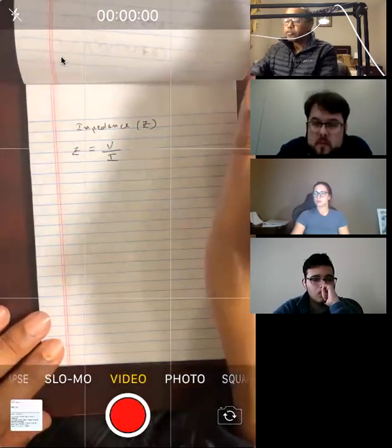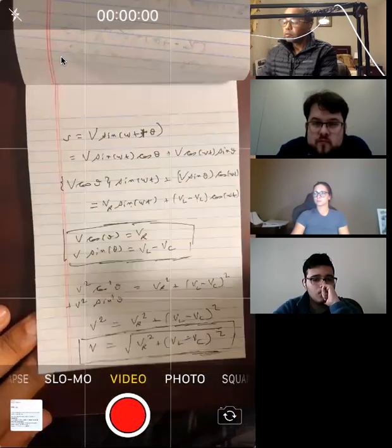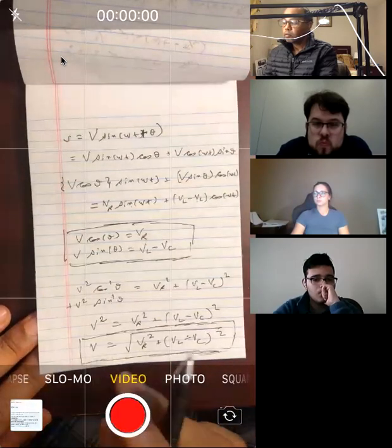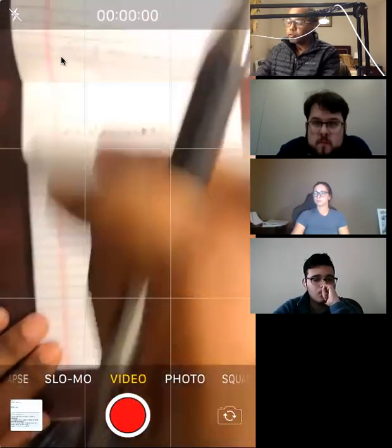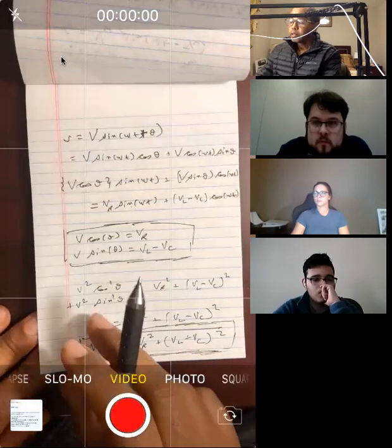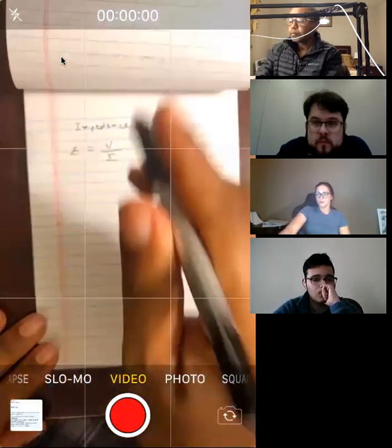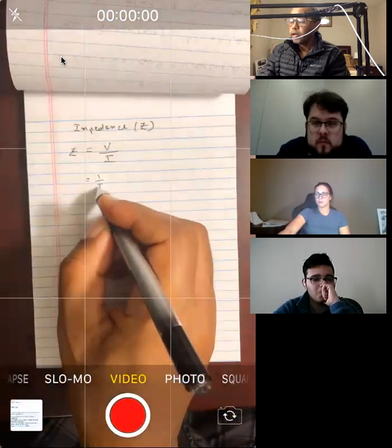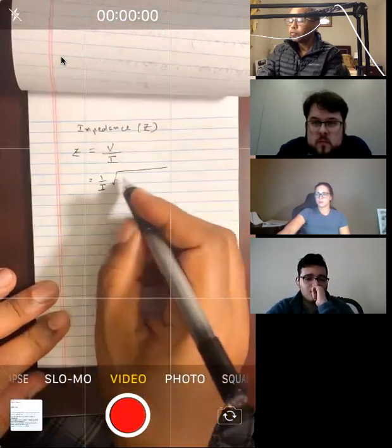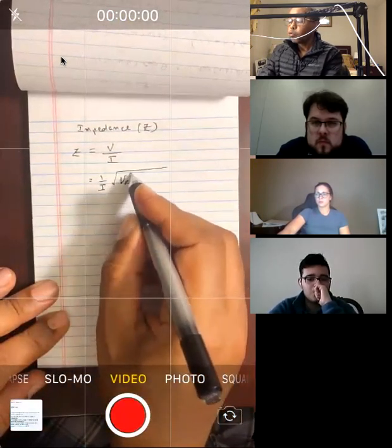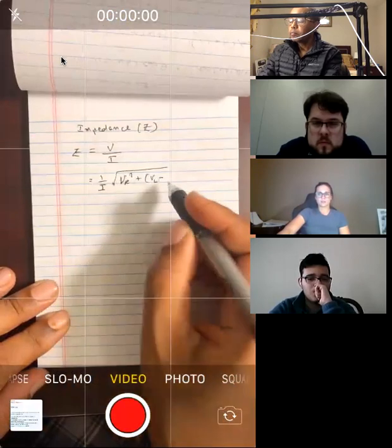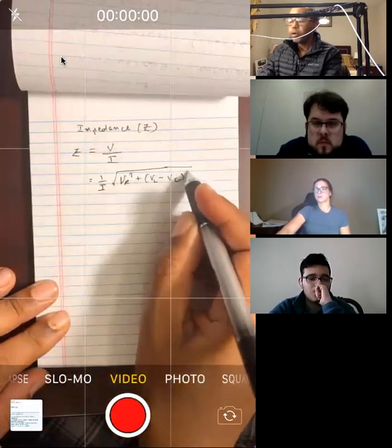But we have an expression for V. It's right over here. So this will be 1 over I times the square root of VR squared plus (VL minus VC) squared, right?